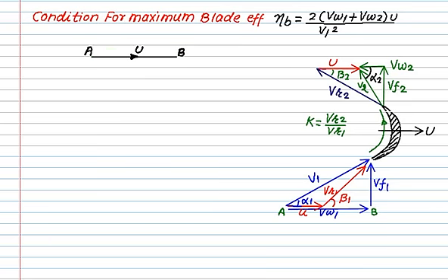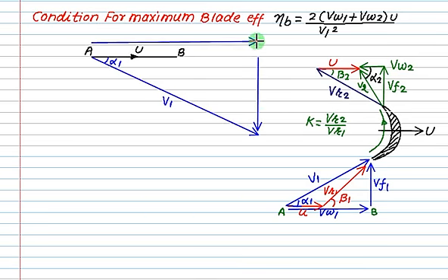At this one the nozzle is inclined at an angle equal to what? Alpha 1. And this one is the blade velocity equal to u1. So it has two components: one is velocity of whirl and one is velocity of flow. Let's say this value equals C, this one is D, this component is VF1 and this is VW1. VW1 is cos and VF1 is sin.